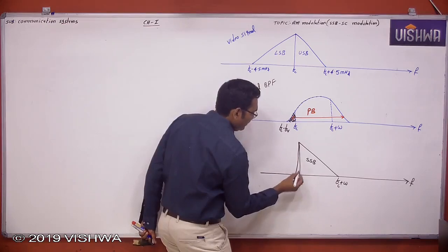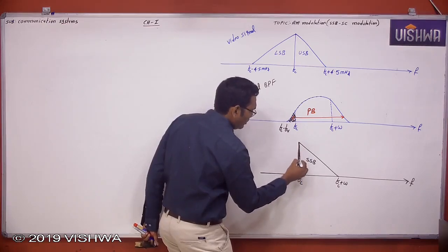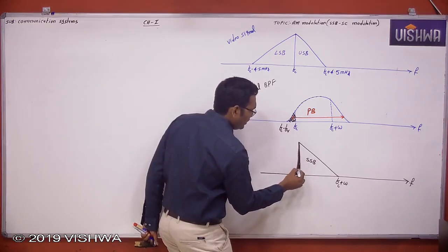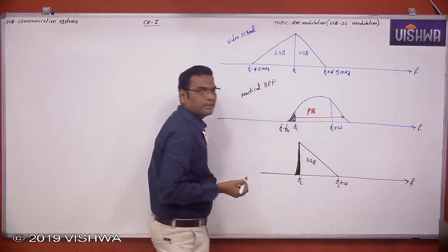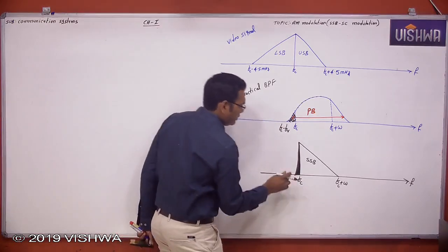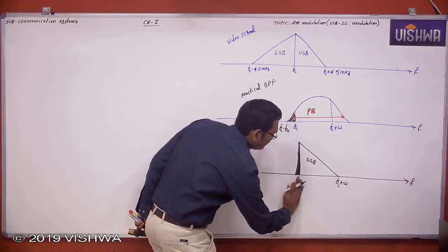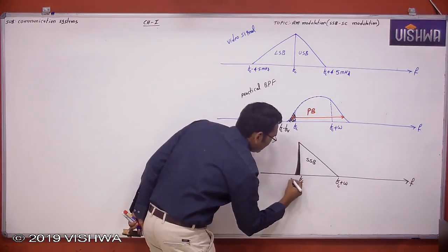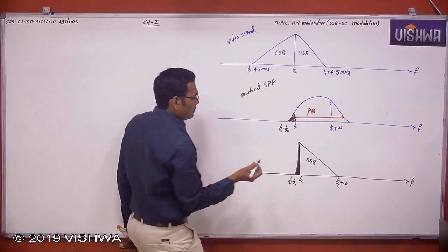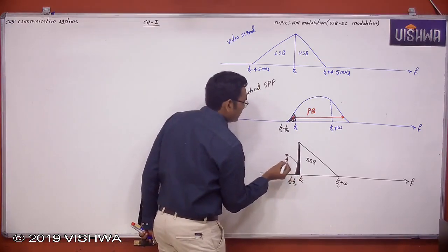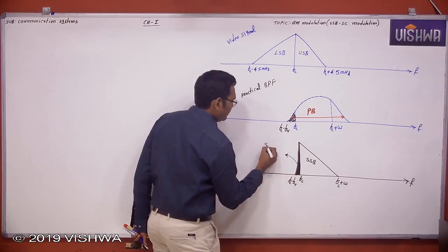We cannot eliminate that small portion, because there is 4.5 megahertz from the other side. It should be minimized as much as possible when designing. That depends upon the designing of the filter. So if you design this filter with appropriate care, this is Fc and this is Fc minus Fp. This is single sideband and this is a small portion.